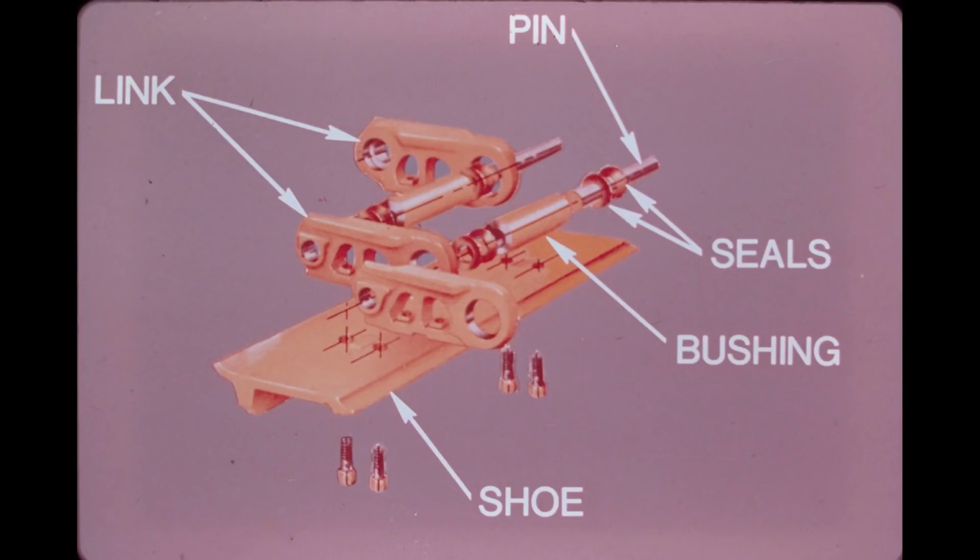The track chain consists of 2 rows of individual links joined with pins and bushings. The links are made of drop-forged, heat-treated steel and have a large bore at one end and a smaller counterbore hole at the other. The bushing is pressed through the large bore and rides within the counterbore of the mating link. 2 concave metal spring washers protect the bushing and link surfaces from galling and keep out harmful abrasives.